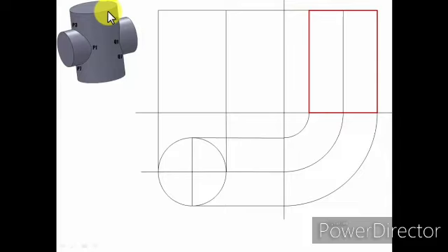We'll now go ahead and create the projections, that is front, top and side, of this horizontal cylinder. For that you need to think, from where can you see the true shape of the base of this horizontal cylinder? One thing is for sure, the true shape of this circular base can only be seen from the side, that is from the left hand side.